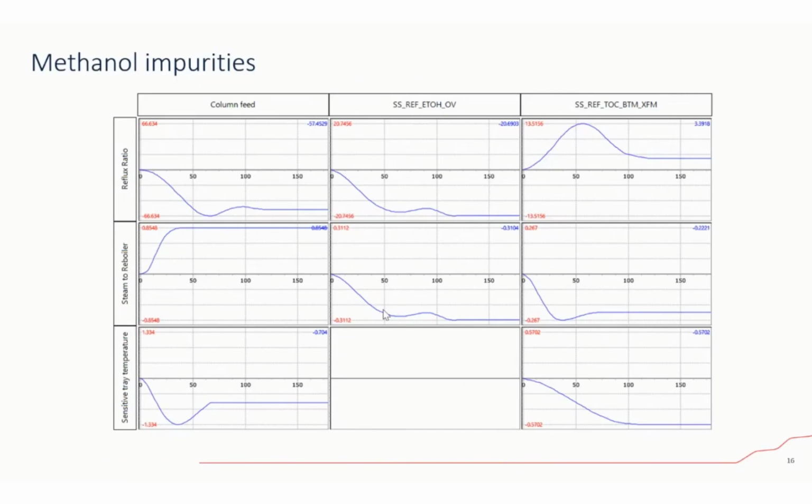So if your objective is to maximize the amount of impurities in the top of this column, but at the same time you want to keep the feed to the column constant, and keep the impurities in the bottom as constant as possible, then you can imagine there is no way you can use a single input, single output approach for this kind of problem.